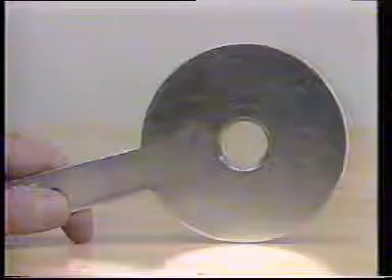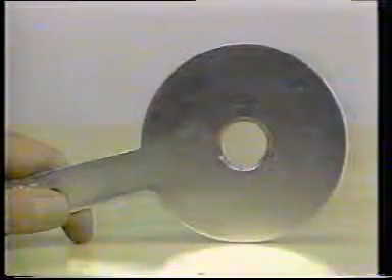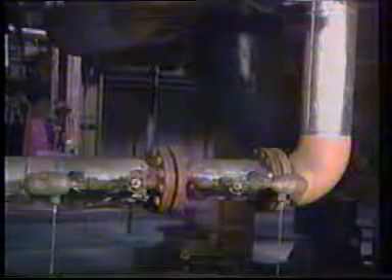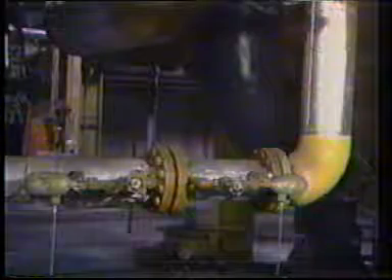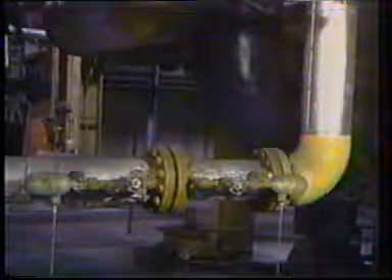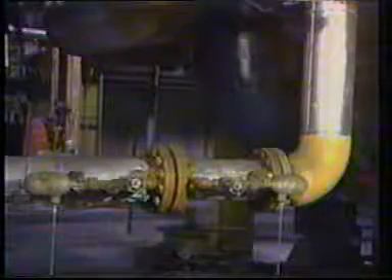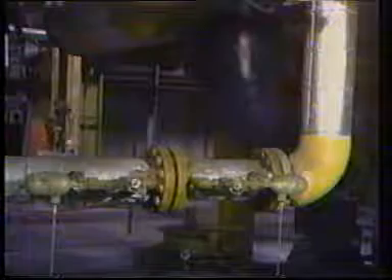Orifice plates have several advantages that make them appropriate for a wide range of applications. They are capable of metering either gas, vapor, or liquids with a high degree of accuracy. Since they're capable of being used in systems that contain either gas or liquid, and because the taps may be located in the piping or the flange, there are several different orifice designs. The most common design has a small hole machined in the center and is called the concentric bore.